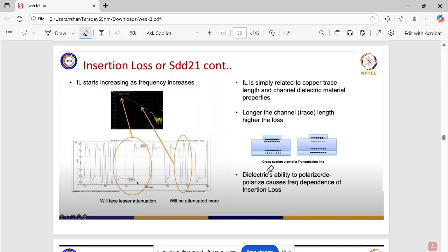When we look at the bit diagram, there are multiple zeros followed by multiple ones. It is very low frequency because the time period is high. When the bit pattern is a continuous sequence of 0 and 1, the frequency is high. So actually we are transmitting a wide range of frequency, it is a wide band. So when we transmit the low frequency, the attenuation of the media to this frequency corresponds to this side of the spectrum, the left of the spectrum.